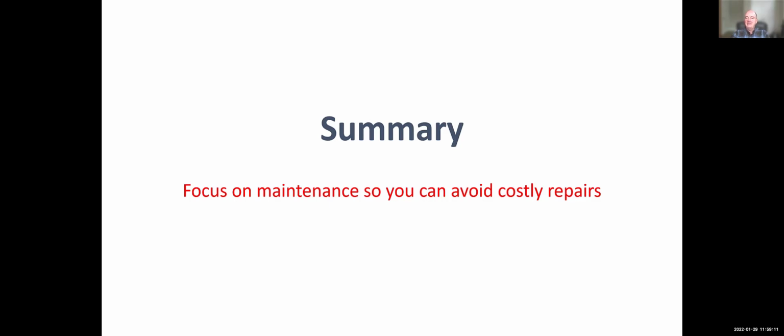Because you might have noted that there was some seepage at some specific location in the past. Well, an engineer that's hired to review wants to know where that was and when it occurred, and what did you do about it. So recording is important. And how much seepage? Yeah, right, how much?